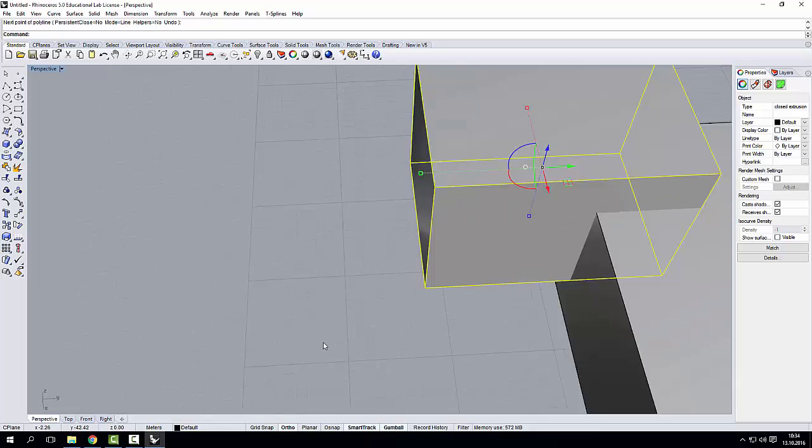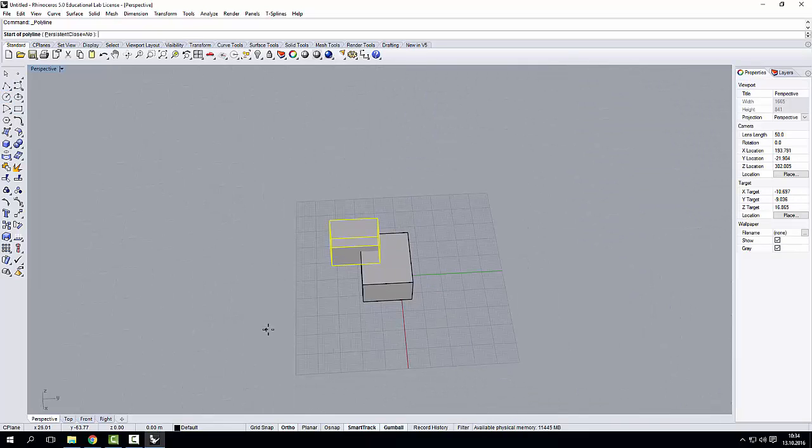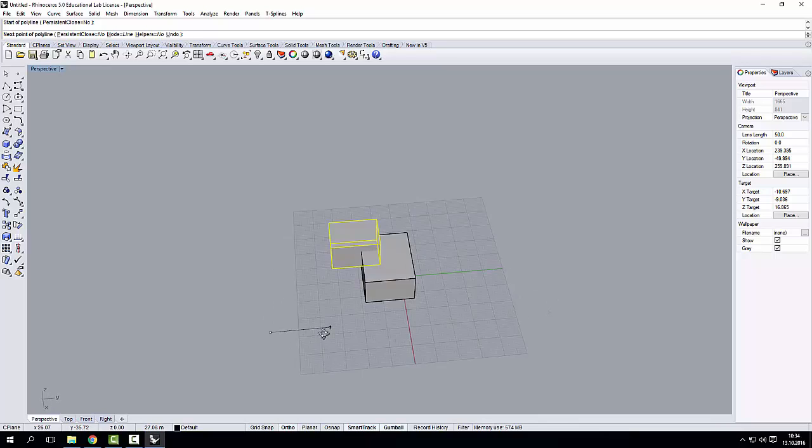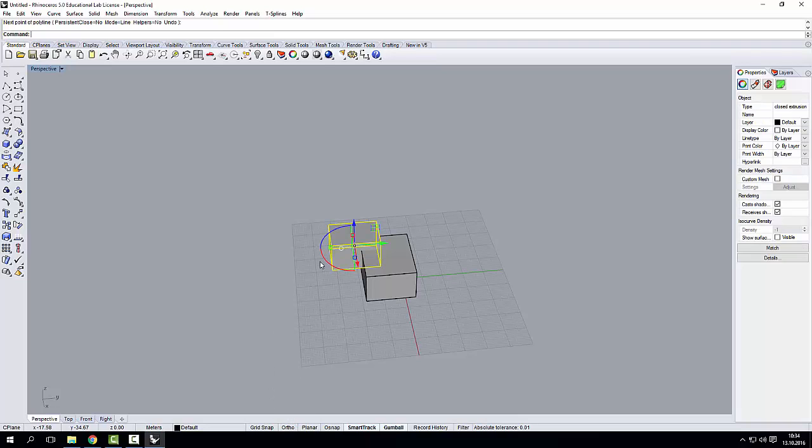The ortho mode allows you to draw in ortho mode. Eventually, with this ortho you have to be careful, because if you have snaps that override the ortho mode, the line won't stay straight, okay? There are other techniques that we are going to look into in depth later to improve the way you draw. I'm going to switch off the ortho mode. I don't really like to use it. There is another technique that I use which I think works better and it's a little bit more dynamic.